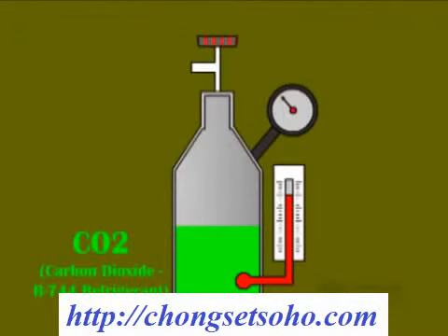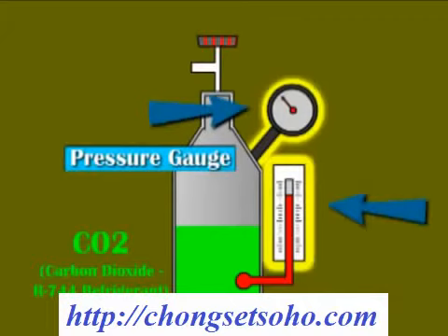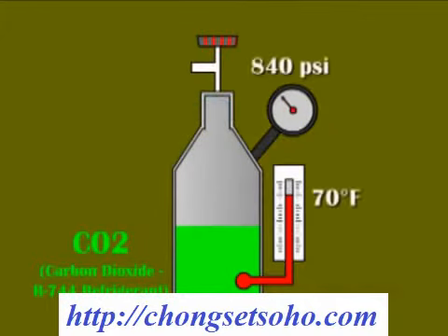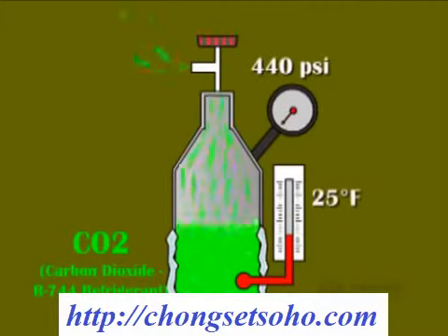All air conditioning systems, including heat pumps, rely on the refrigerant's pressure-temperature relationship. When a refrigerant evaporates, or boils, it absorbs heat at a very high rate, as is the case with all liquefied gases. Since refrigerant has a lower boiling point than most liquids, we can easily manipulate it so that the only heat source needed is room temperature air. We can control this boiling point by altering the pressure placed upon the liquid.